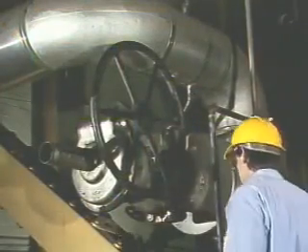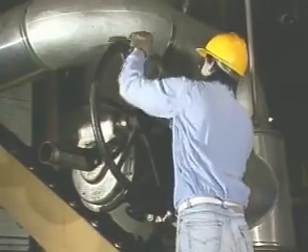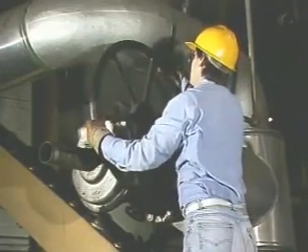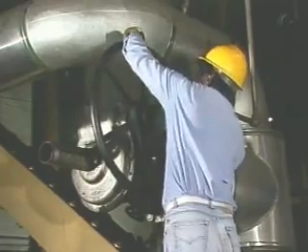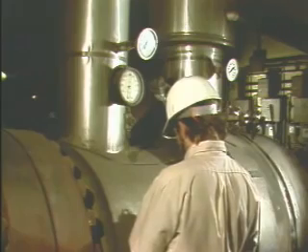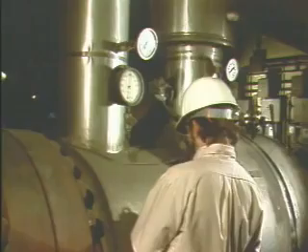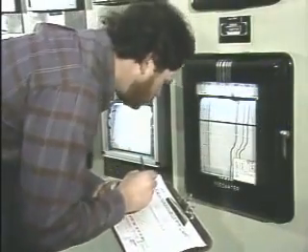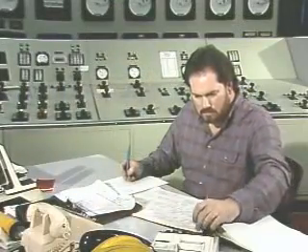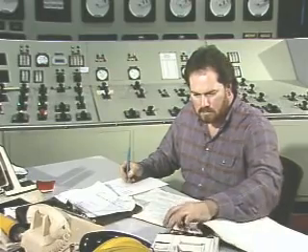A large tube leak is a serious problem that calls for immediate attention because it can allow water to enter the turbine. To prevent damaging or destroying the turbine, you should isolate and bypass the heater as soon as possible. Of course, operating with even a relatively small tube leak is inefficient, so it's important to find small leaks early and get them corrected. Small tube leaks may be difficult to detect, though, because they don't show up on instrumentation. But some small leaks may become noticeable when you calculate the TTD and the DCA for a heater.